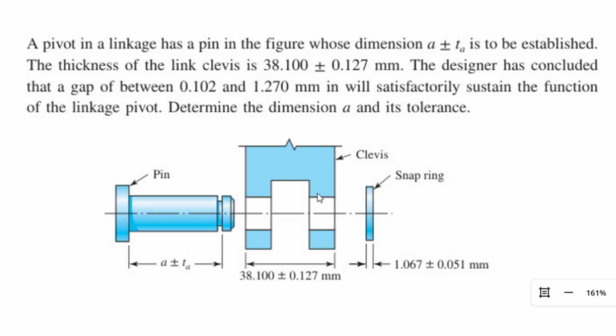Our job is to determine the pin dimension and its tolerance, so the gap stays within the acceptable limits that the designer has basically specified. This is a textbook tolerance stack-up problem. Small variations from manufacturing add up and can make or break the assembly.